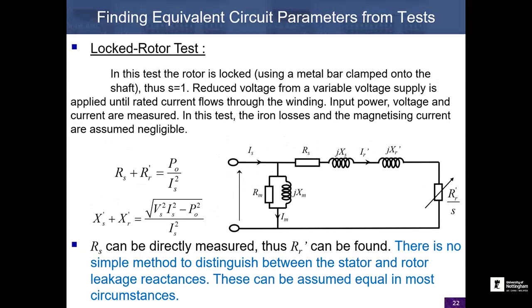Our second test we commonly apply for an induction motor is a locked rotor test, and this is a physical process where we lock that rotor, we bolt it down to prevent it moving, and that means we've set our slip as always equal to 1.